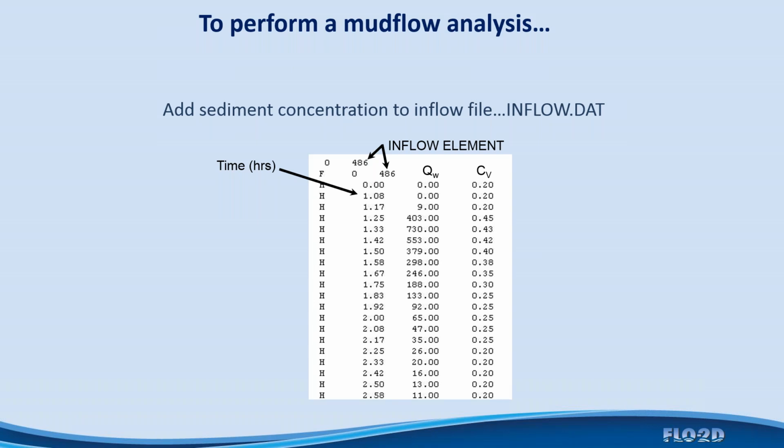And then after that, I decrease it, even though you might have a few waves after that that bulk up a little bit as you get this kind of resurgence and surging of the mud flow coming down. I basically decrease the concentration by volume on the rest of the hydrograph back down to about 20% concentration by volume. So even when the event is back down to 10 CFS or so at the end of the hydrograph, it's still flowing something on the order of 20% concentration by volume.